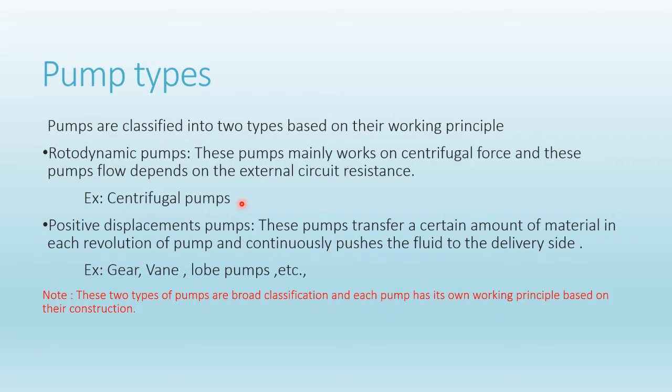In this, the vacuum is created at the center of the pump, called the eye, and the material is pushed out of this eye to the external casing. So the material is pushed from the center to the outside. This is called centrifugal force. The material pressure increases due to the presence of the vanes, and the material is transferred through the vanes by centrifugal force. That's why the main principle of rotodynamic pumps is centrifugal force. So generally rotodynamic pumps are centrifugal pumps.